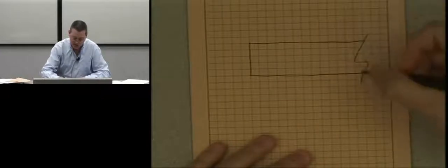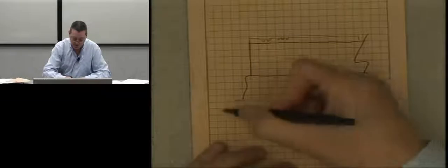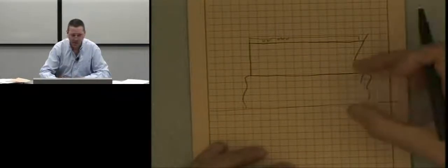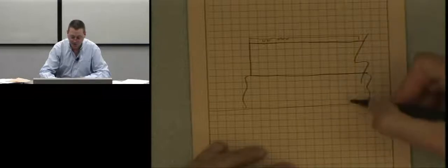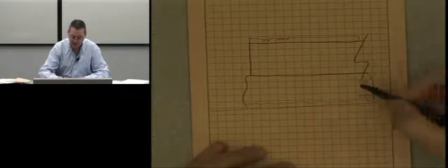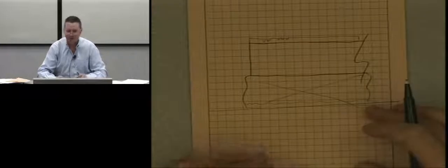But solder now, if you look at a modern IGBT that's, let's say, 70 microns thick, and I'm just drawing a cross section here, and here's all the junction engineering on top with the trenches and so on. The solder itself is about 50 microns, and then you've got the back plate. So this becomes a limiting factor. So the technology trends now are to make the die thin, of course, but then to use techniques like sintering. So this becomes 10 microns instead of 50 or 60. So some interesting work going on there.